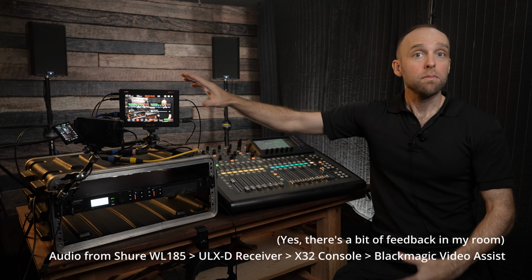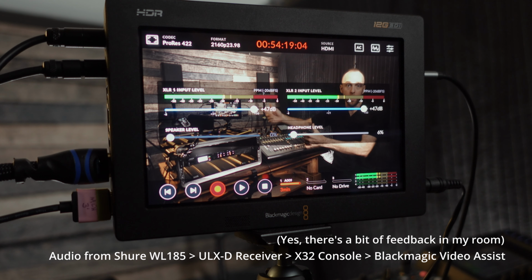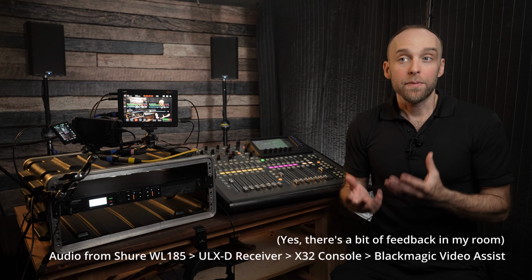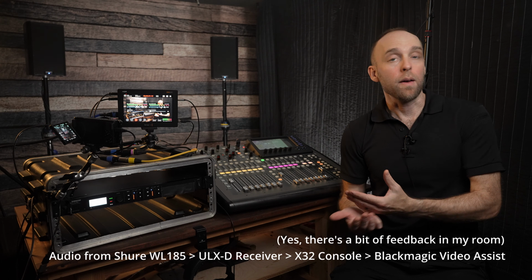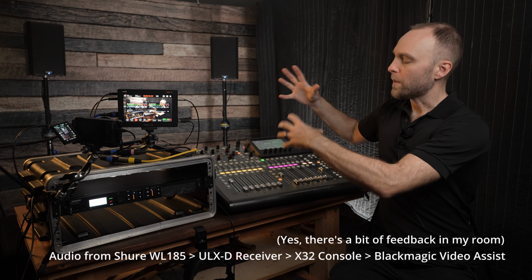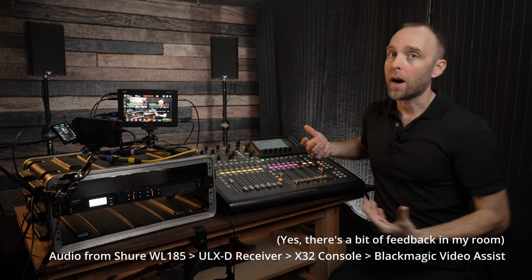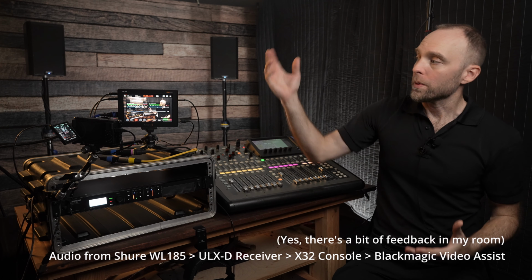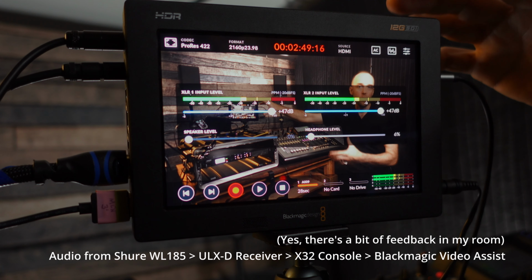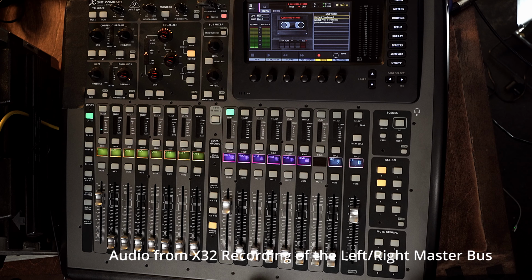But recording devices receive the same level. They have to use their own internal input gains to gain up, and they are also now amplifying all of this noise. And this is one of the fundamental problems that I see from live audio engineers, is that they're gain structuring for volume of their speakers, while completely ignoring the electrical levels and resulting in this noisy audio. And one might think, okay, well, yes, we had to gain our external record decks up, but that's the record deck's fault. Not really, because now you're actually hearing the internal recording from the console itself.